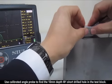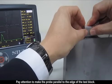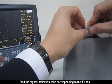Use the calibrated angle probe to find the 10 mm depth Φ1 transverse drilled hole in the test block. Pay attention to make the probe parallel to the edge of the test block. Find the highest reflection echo corresponding to the Φ1 hole.